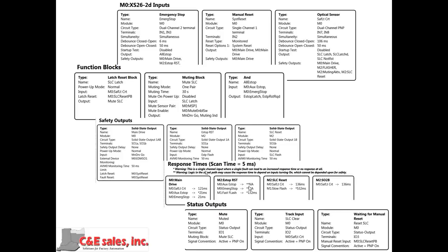You will also notice a couple of these that have NA on them. This is because in my flasher circuit, I use a transition of an input 0 to 1 rather than 1 to 0 to turn off that output. And this is a warning from the Banner folks that says, hey, we typically do not in safety circuit design use a signal 1 or a positive power input as a stop signal.